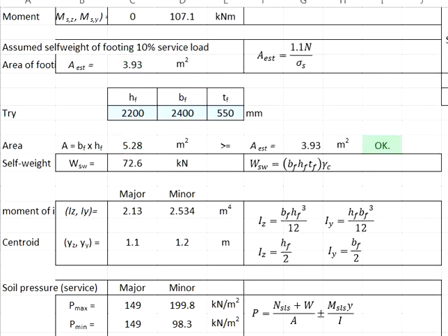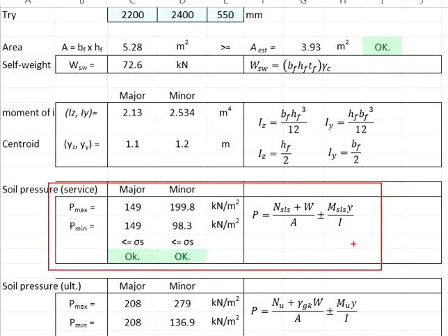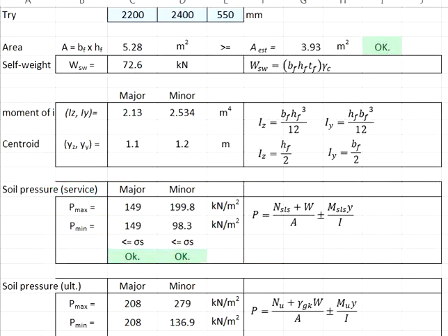So, as far as soil bearing capacity, without considering the influence of the moment, it should theoretically be adequate. However, we are not sure at this moment, since we haven't considered the influence of the moment. Our next step will be to confirm the soil pressure not exceeding the soil bearing capacity.